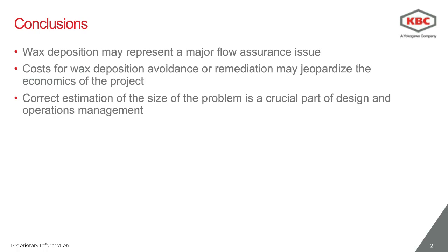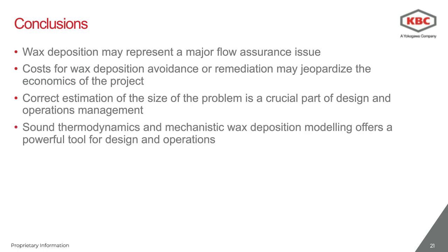for the design and for correct operations management in the presence of wax deposition. However, in order to achieve this, sound thermodynamics and mechanistic wax deposition modeling is necessary to predict reliably the effect of wax deposition. Normally, wax deposition and wax separation predictions are trusted so little that most operators would just not rely on any simulation approach.